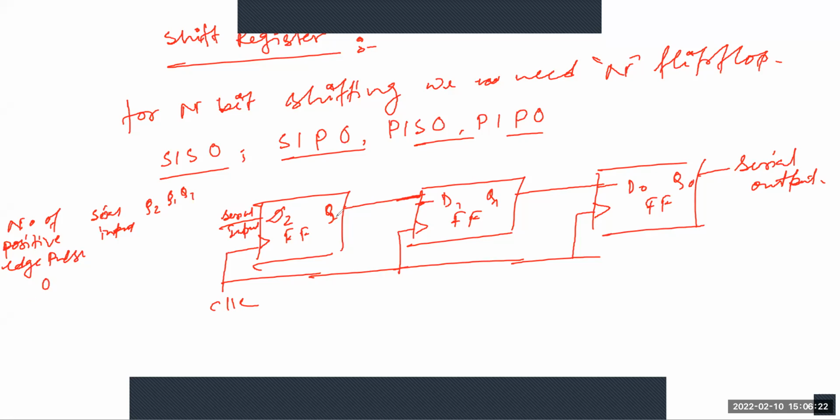So here this is 0. Here we are considering a 3-bit SIPO register, sending the binary information 0 1 1 0 1 1 from the left-hand to the right-hand side. The initial status of Q2, Q1, and Q0 is 0 for all three. Now I am giving 0, so there is no serial input, and at this point the value of Q2, Q1, Q0 is 0 0 0.